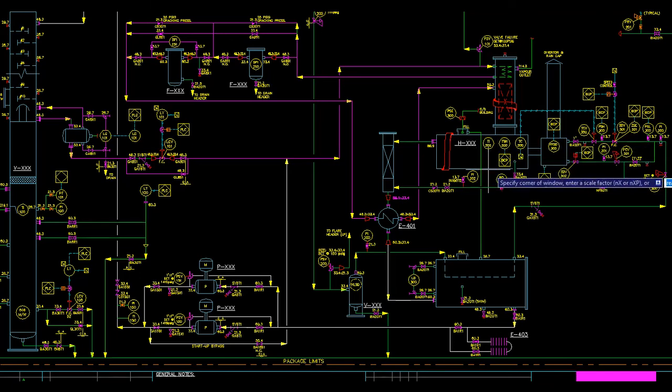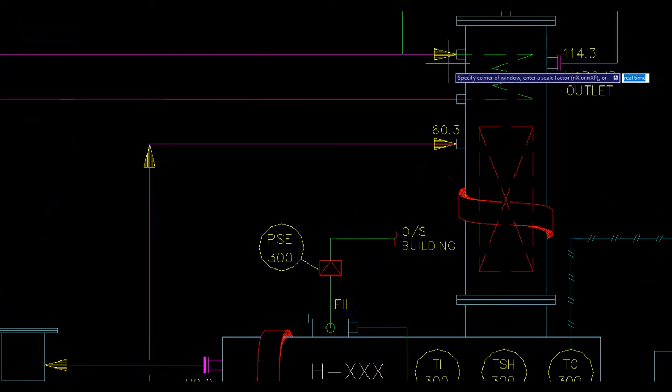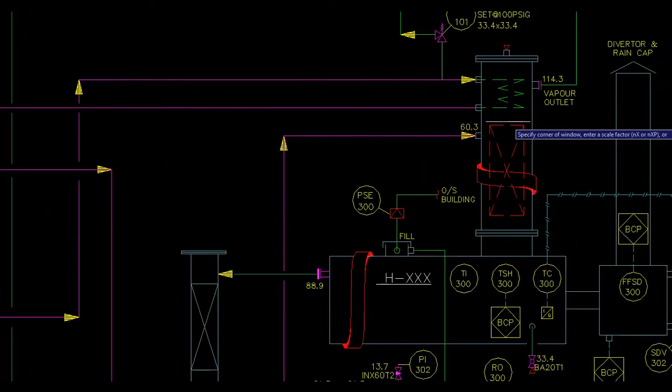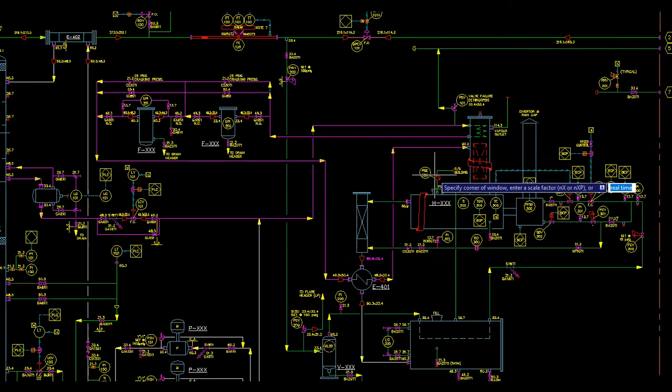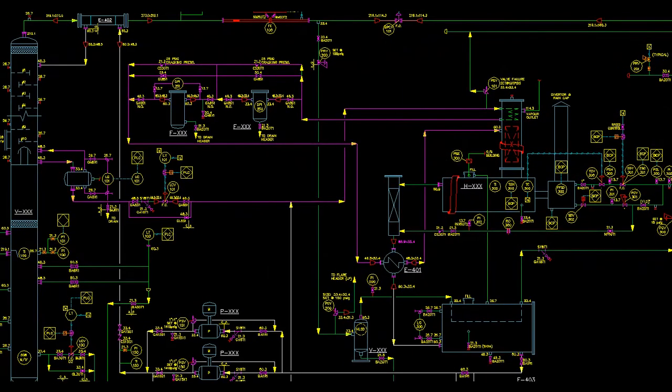Notice the little coil here and the heat exchanger here. These two will reduce the lean glycol temperature and increase the rich glycol temperature. I'm aware for a new engineer the words are confusing: lean, rich, temperature, pressure. You'll have to go through the process a couple of times to get used to it.